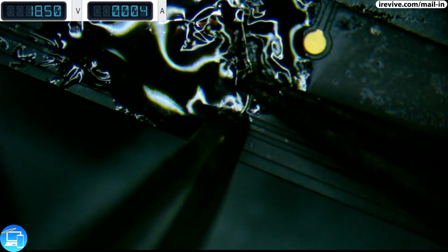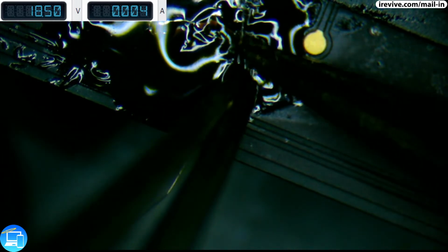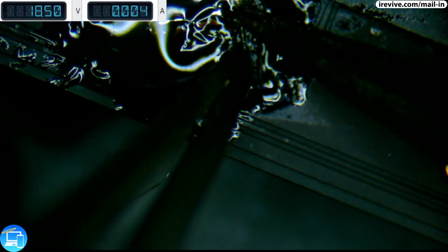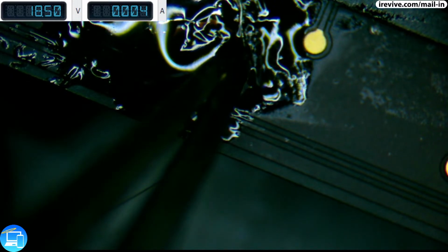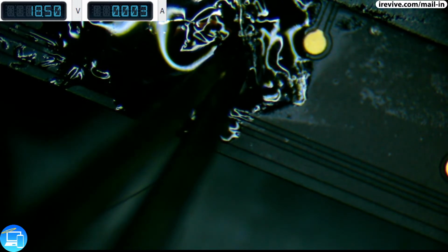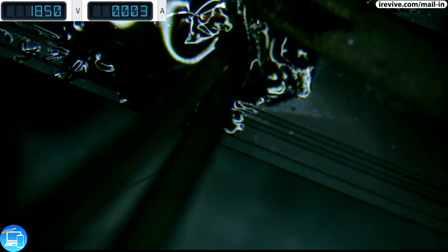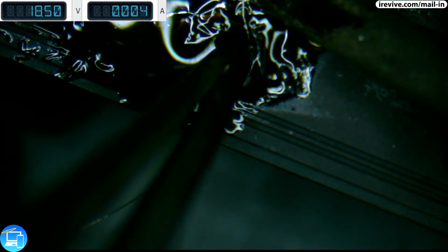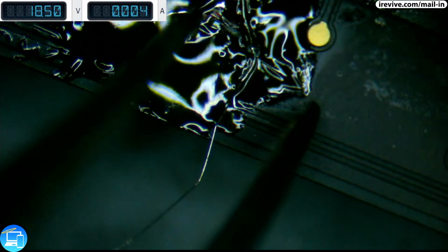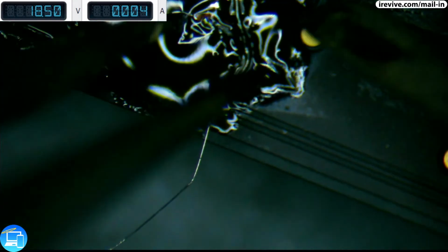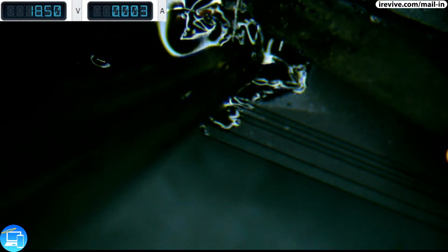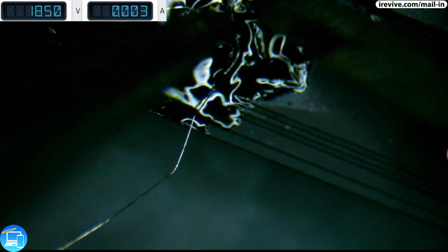And the longer that you solder on flux, it starts to get this very thick, again, molasses or caramel-like state. Okay. And then now I need to try to solder onto that tiny little dot right there in the center.